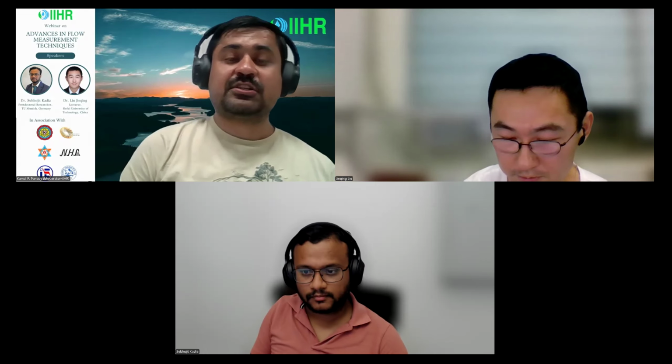Okay, maybe you can write in the chat also. Also, I would like to say that there are certain large scale particle velocimetry methods which can be used. They do not exactly give you the depth, but they can give you the 2D flow field. You can place a camera on top of a bridge or somewhere in a stable place and continuously take pictures, and then you can generate the velocity vectors on the top. Assuming that you have a known geometry below, you can extrapolate the velocity field on the cross section and then estimate the flood.